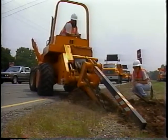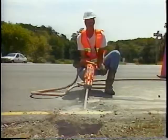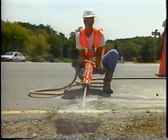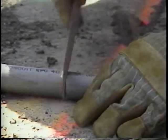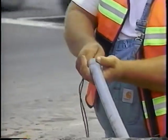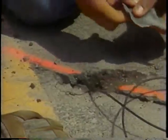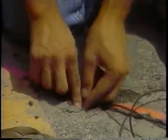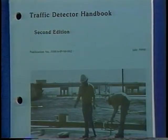At intersections with shoulders, as in our example, dig a trench from the pull box location to the pavement. Then, at a 45-degree angle, core drill a hole at least 6 inches from the edge of the pavement into the trench. Next, cut 1-inch, thick-walled PVC conduit to the correct length and place in the core hole. Run the wire through the conduit and then the conduit above the drainage line to the pull box. Then place duct seal at the pavement end of the conduit to keep out saw-cut sealant and to facilitate any future maintenance on the wires. Refer to your handbook for other curb and shoulder crossing techniques.